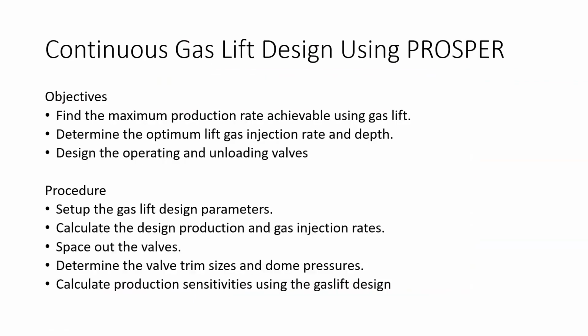Okay, so this is the design for a gas lift using Prosper. The objective is to find the maximum production rate achievable using gas lift. Then we need to know the depth and injection rate for the optimum gas lift, and also design the operating and unloading valves.